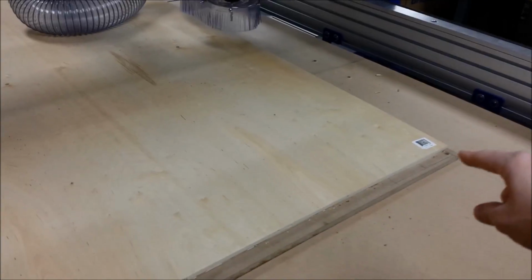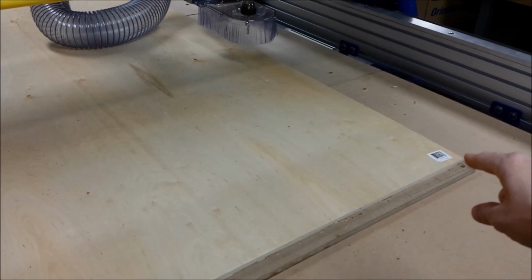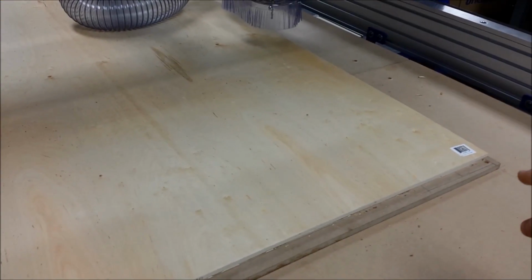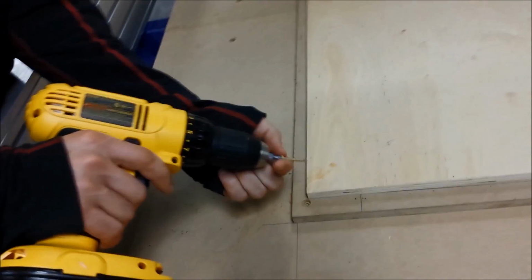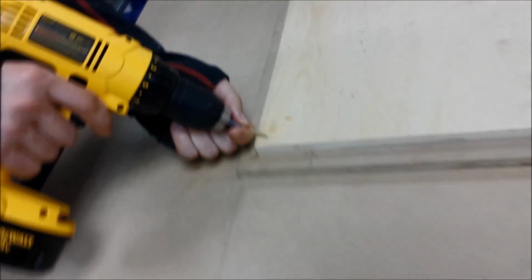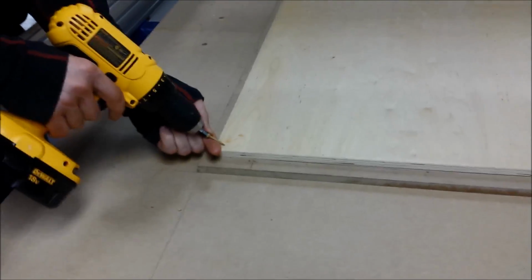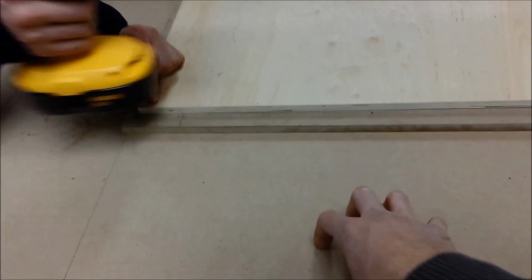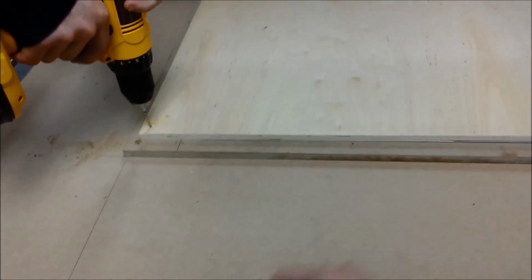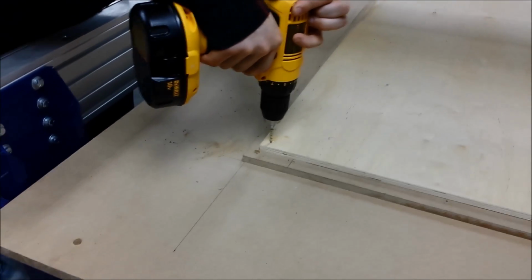And so we can do our Z-axis over here, or our 0 over here, and still not hit our other places if we wanted. But the way that we're mounting this is we're screwing this directly down into the sacrificial material. And so we're using some pretty nice self-tapping screws, and they use a star bit. This is a 1 1/4 inch screw, and it's going through a 1/2 inch on top and a 1/2 inch here, and then of course whatever the bottom piece is, it's just going to be whatever's left.